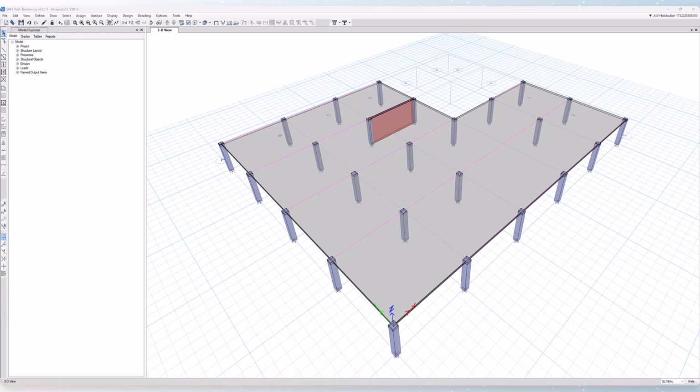They are non-structural geometric objects defining an area of the slab. They would normally be bounded by support lines, but are currently used in the program for 4 different purposes: automated pattern loading, summary table of maximum displacement results within the slab panel, summary table of maximum soil pressure within the slab panel, and meshing lines along the edge of the slab panel.